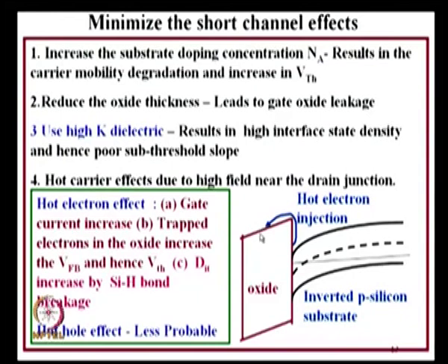you can have electrons injected into this dielectric. You can consider them as hot electrons, and once they are injected into the dielectric, they can act as additional traps in the dielectric that can change threshold voltage and give rise to reliability problems. So, what you have to take care of when you go for dielectric materials is not only that it has a good band gap, it must also have this gap between the conduction band, that is the chi.